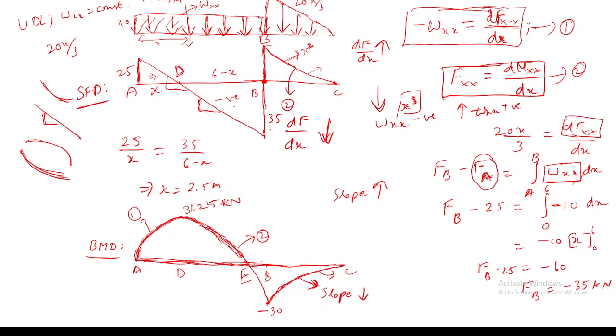Here, for example, the load intensity decreases, so you are calculating the slope value as a decreasing slope. You are not considering whether it is in the downward or upward direction. But when you use the integration formula, at that time you have to use the sign convention, downward as negative and upward as positive. Only if you practice these problems will it become very clear.